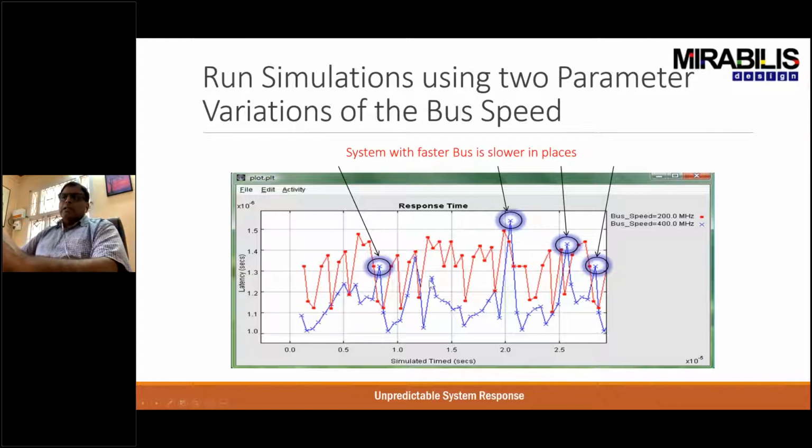What are those? These could cause buffering of the future events. That could be one. These spikes could cause increased power consumption. That relates to thermal cooling, so you have that impact. And the third one is these might be beyond the timing deadlines, which means it's not within the acceptable range in which the system needs to be operating in terms of response time. So that's the kind of thing that you can analyze from this.